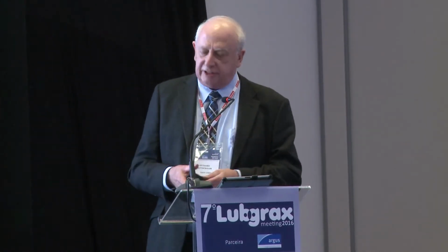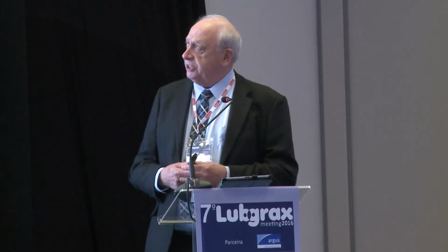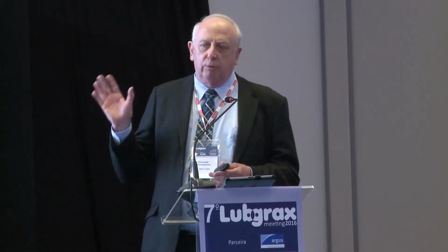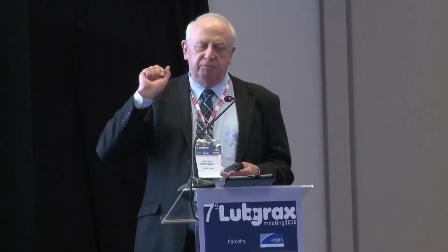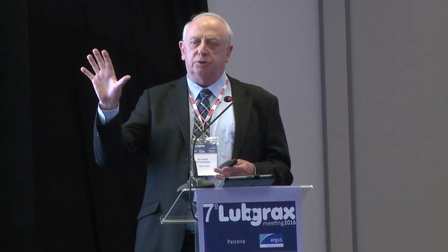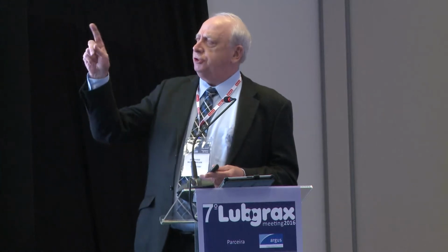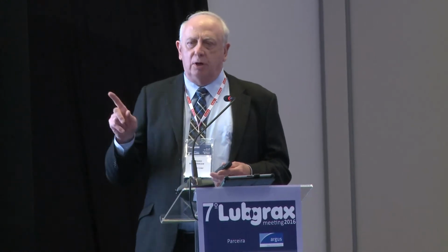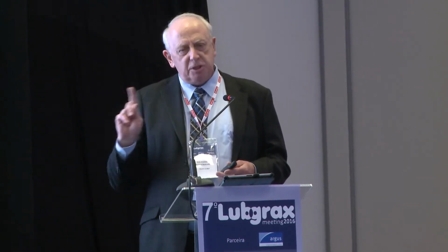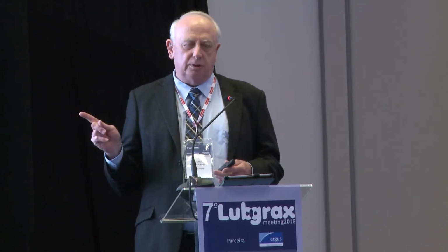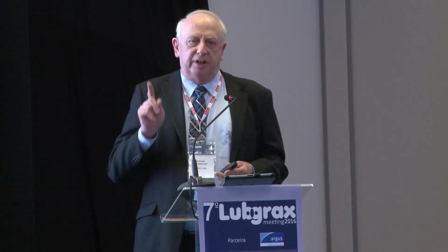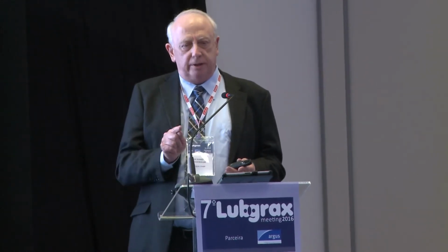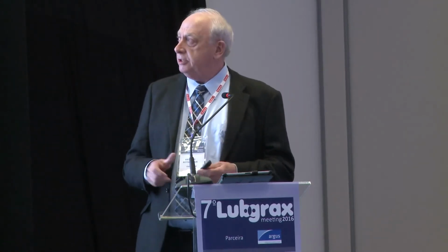I've been around in this industry a long time. If somebody had asked me as a microbiologist 30 years ago about health risks of bugs in metalworking fluids, I would have really tended to say that the published literature doesn't support the health issues. And that's true in relation to infection risks. Organisms like Pseudomonas, and that's a name you've heard quite a few times, in a hospital environment are very serious. People die in hospitals from Pseudomonas infections. But there is no published evidence that Pseudomonas in metalworking fluid causes infections in operators. So it does not appear to be high risk.